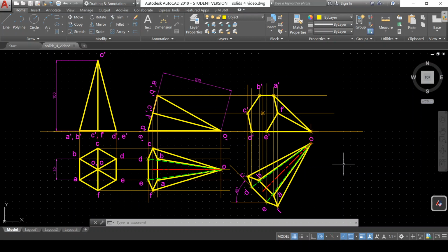Now what is clearly visible? Can you see DO? No, because it is resting on HP, so that is actually behind EO and it is overlapped. So that is done. Next thing, can you see other edges, that is CO and BO? No, CO is far away and similarly BO is also not nearer. You are seeing it from this side, so both will be hidden.